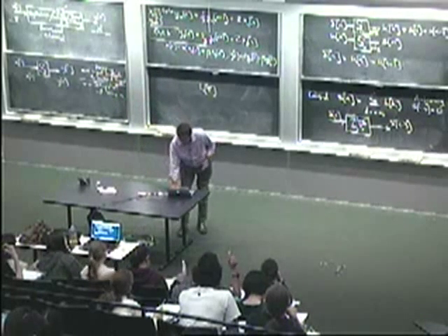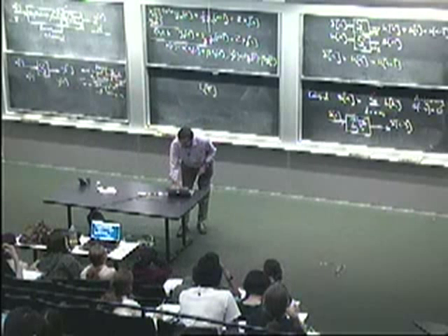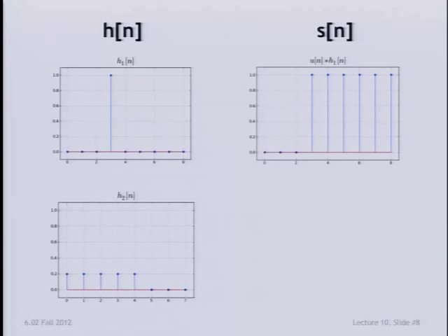Okay, this takes a little getting used to, but let's do another example here. So here's another unit sample response. This is more complicated now. I put in a unit sample, and what comes out is a response that still starts at time 0, so I'm talking about a causal system. Everything to the left is 0. And this takes the value 0.2 for some number of steps, and then settles to 0. So the question then is, what is the step response?